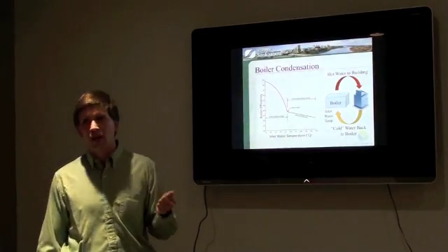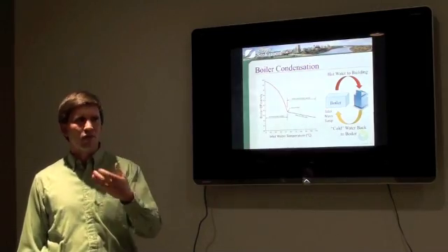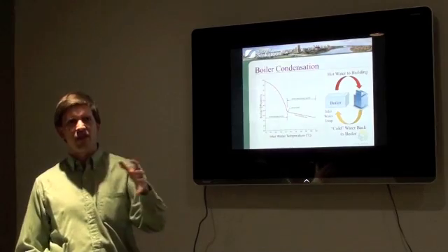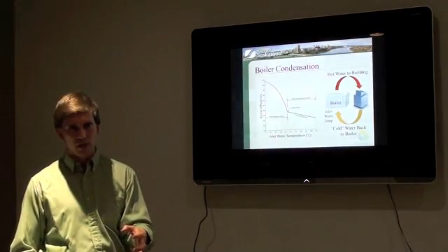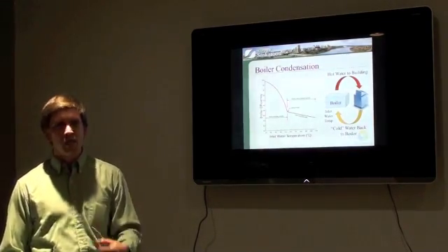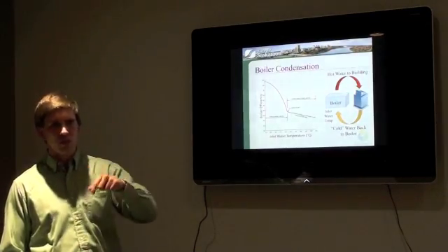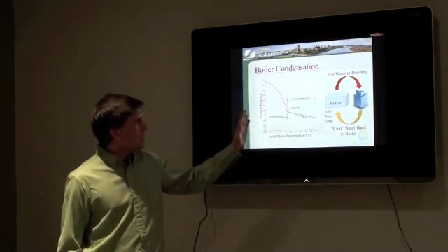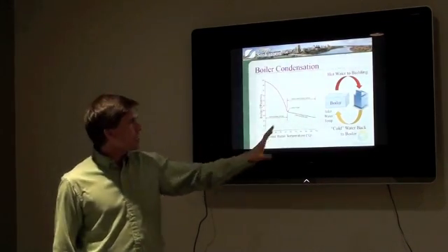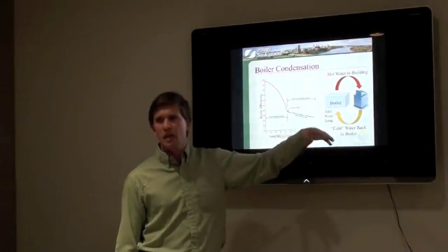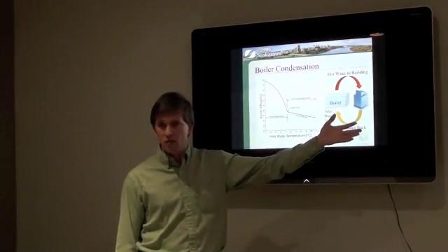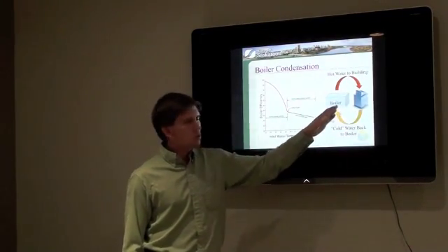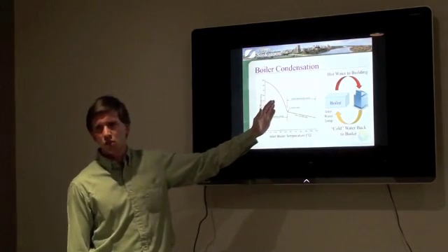Now the Fieldhouse and many other facilities are designed with forced air heaters. You've got coils with an air fan blowing air across, so you've got a very small heat transfer area. A smaller heat transfer area means you need a much higher temperature difference between the fluid that's doing the heating and the air itself. So even with the Fieldhouse, we're finding that if we're not needing too much heating, as in the day temperature is relatively warm, or even say 0 degrees Celsius, the water's coming back cool enough that a condensing boiler is still the efficient way to go.